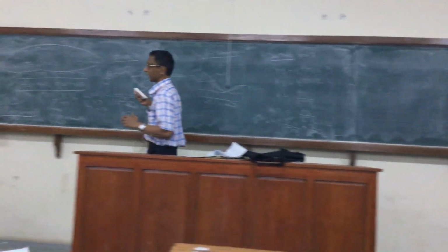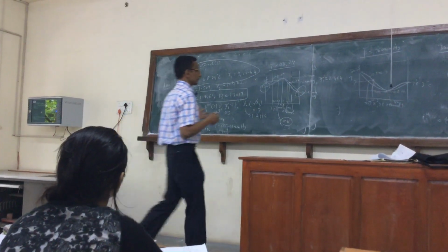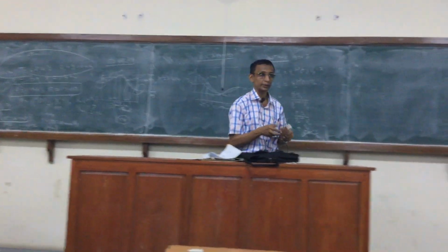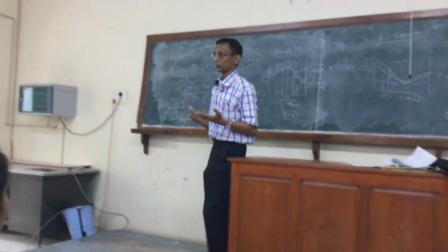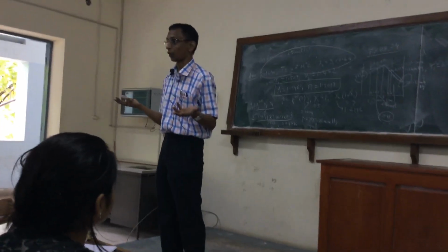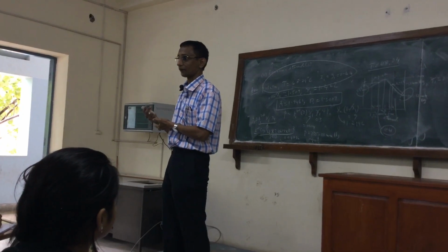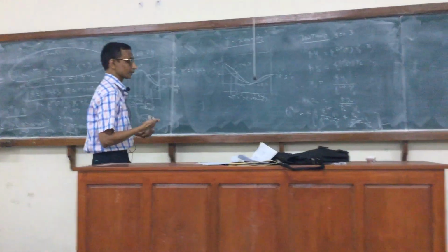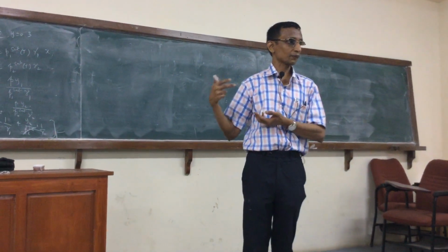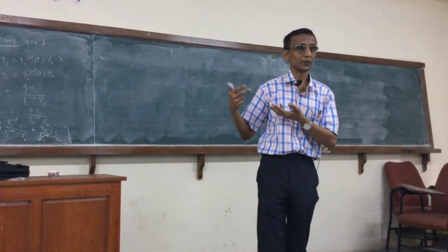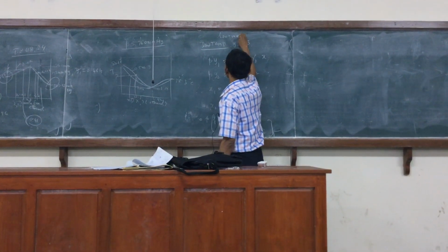But now we go to the next level of complexity, where we say that even for the liquid, we cannot. The main point here is the activity coefficient model includes all calculations with respect to volume. There is no input at all. We don't have to calculate volume, which is one of the major stumbling blocks in the equation of state. So that convenience we have. But what Sandler and others point out is that when you go to very high pressures, you have to have some volumetric input. So the activity coefficient model is basically applicable for low to moderate pressures.